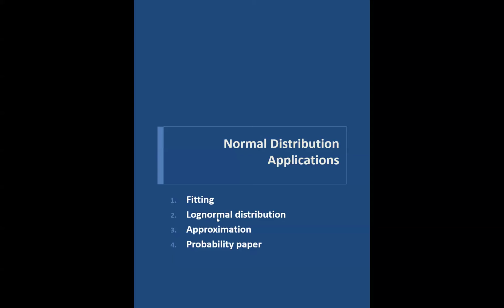Secondly, there is the modality of a normal distribution that for some problems like the fatigue lifetime, the original x is not normally distributed. However, if we take the log of the x variable, then the distribution becomes a normal distribution. So that is going to be the second modality.